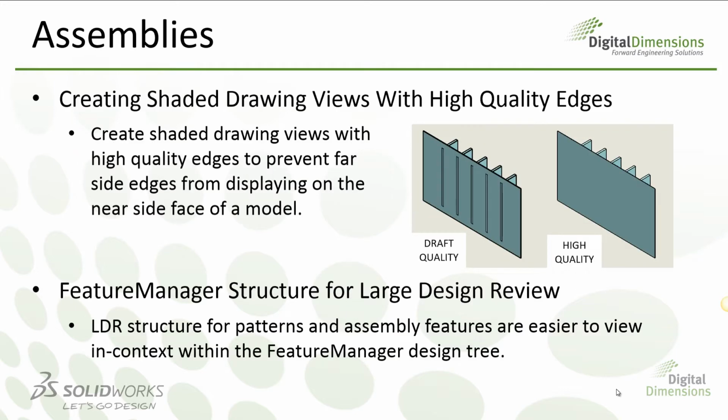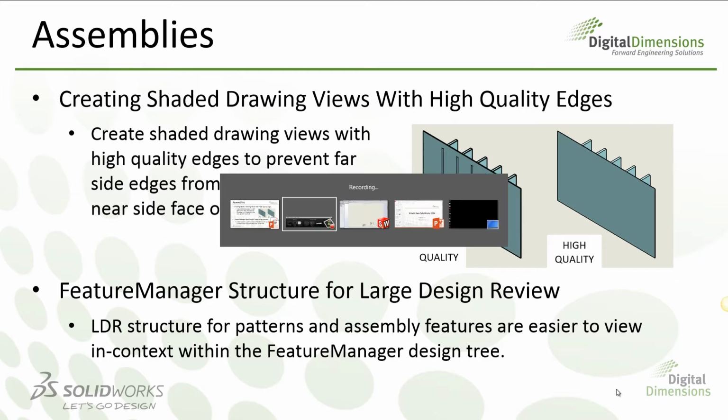The first thing to take a look at is the ability to create shaded drawing views with high-quality edges. In an assembly environment with thin components that mate against each other, in previous versions of SolidWorks you can see that the edges would actually bleed through on the drawing.